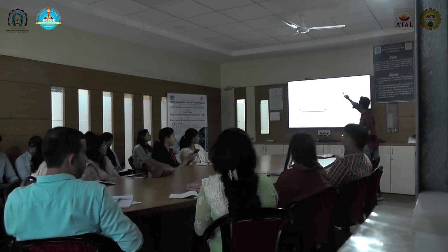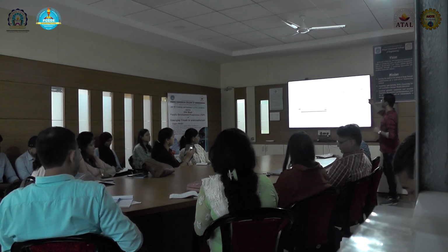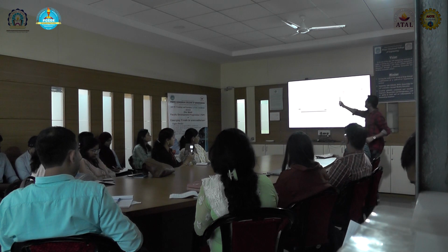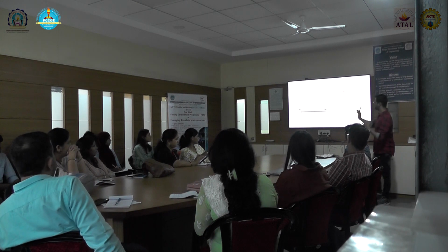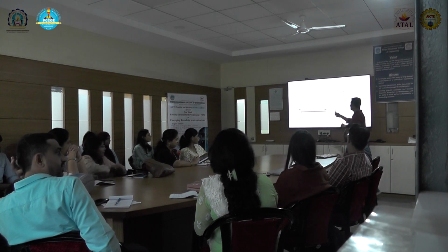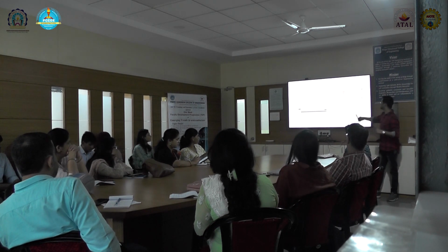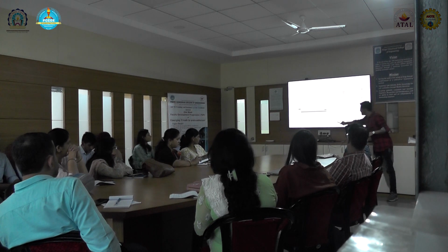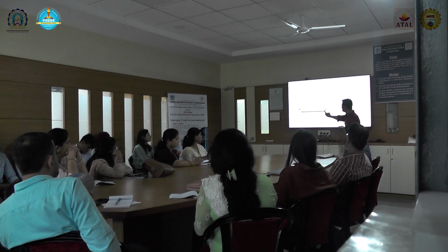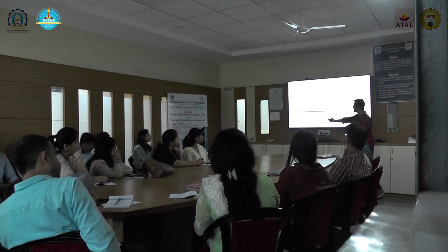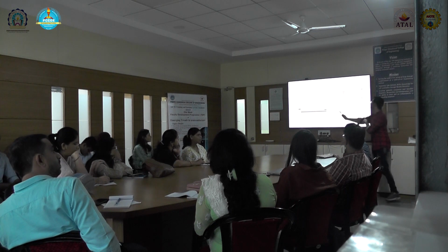In our DUT we have done, busy, rec1 and rec2 as output signals, so we will write a property to check their behavior. From our DUT we know that done should only be high when we have busy, correct? So we will write a property for it, with a name. It's an assert property. It depends upon the clock, and it should be disabled if there is a reset. And what are we checking? We are checking that done should be high when busy is there in the same cycle. We are not checking that busy should be high in the next cycle. In the same cycle when we get done, busy should be high. This is the operator which checks in the same cycle.